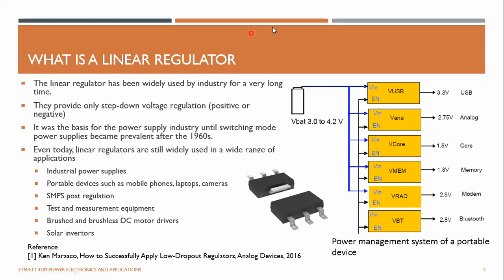That is basically when you have a switch mode power supply, or maybe a buck converter, a high efficiency buck converter, and you can couple a linear regulator. The buck converter, as you know, has high noise. So you feed a linear regulator as a post regulator after the switch mode stage, and this is your output.